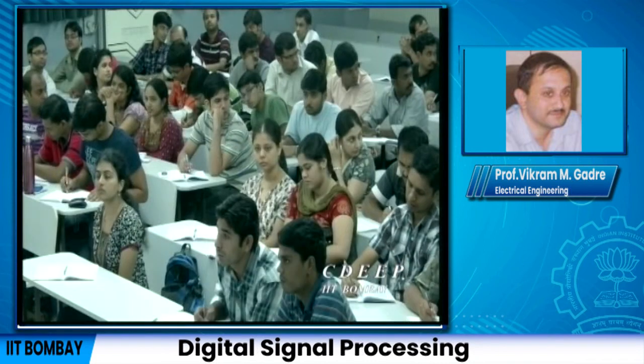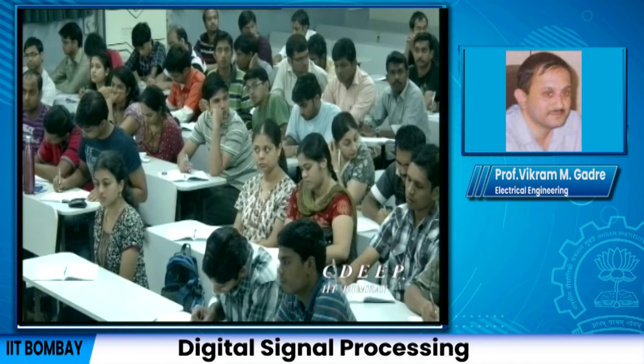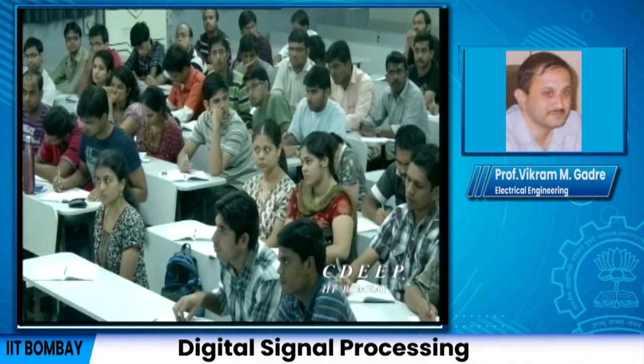Yes, there is a question. When we are calculating energy using this time density, so we have sampled the signal for T equal to 1 only, like unit sampling. Yeah, so the question is, when we calculate the energy time density, we are taking the sampling rate to be 1. Is that the question? Yes, indeed. We have normalized, isn't it? We have normalized the sampling rate. So we have normalized the time axis, and we have also normalized the frequency axis. So of course, when you go back to the actual times and frequencies, you need to bring in that normalization factor. So we are working with normalized time and normalized frequency.